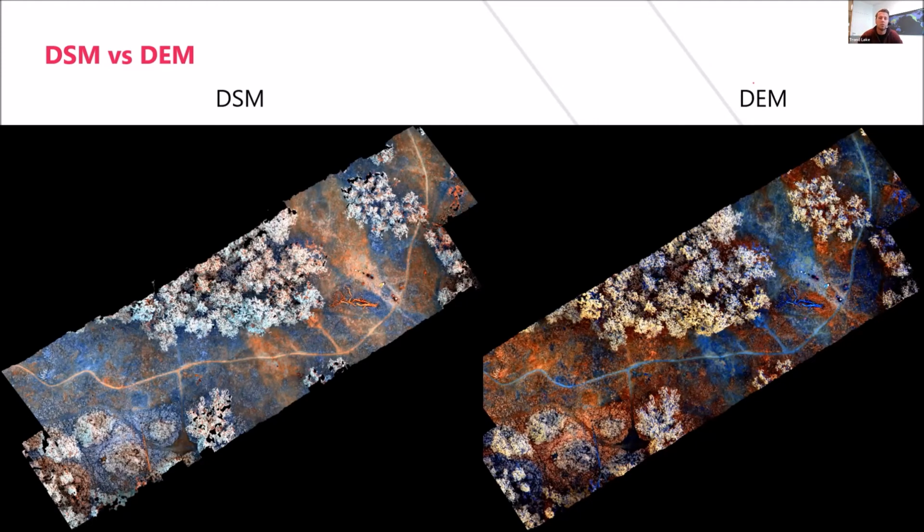Yeah. So on the right side here, I've used an elevation model to rectify two flight lines and mosaic them. You can see you have this trail here. It matched very well. If I could zoom in, you would see that you don't see the overlap here, except for the BRDF effect differences, because we will come back to that, right?